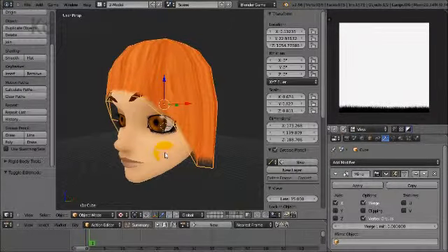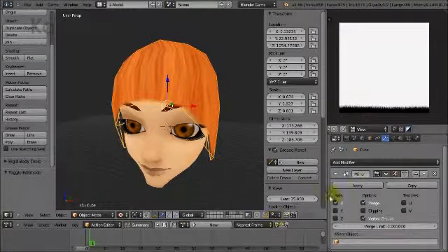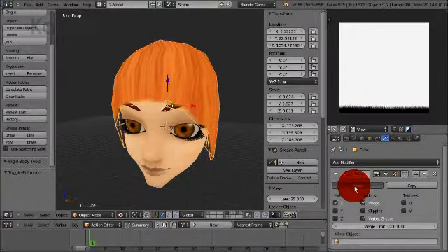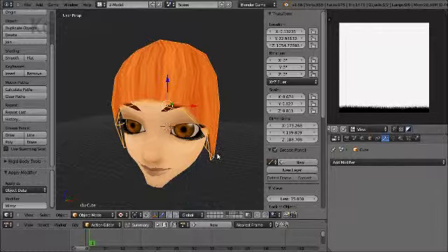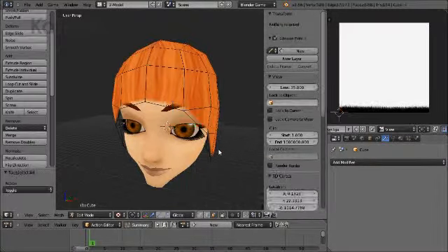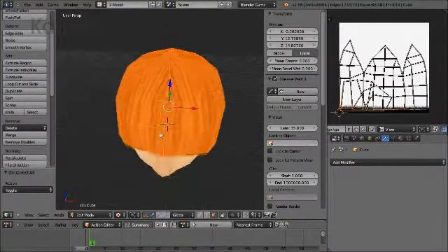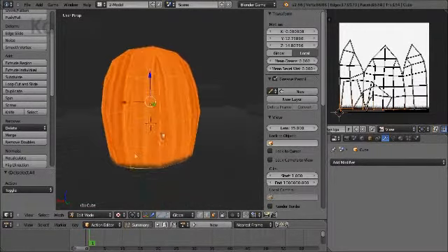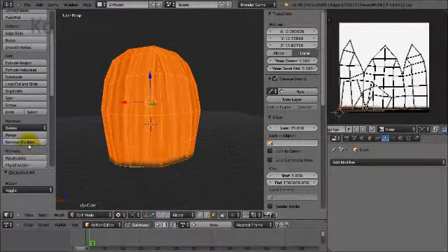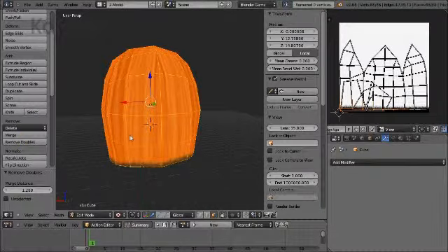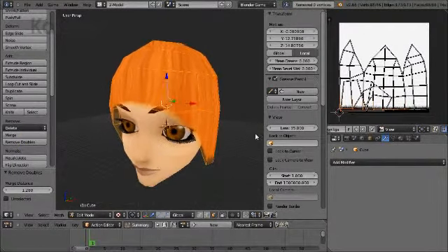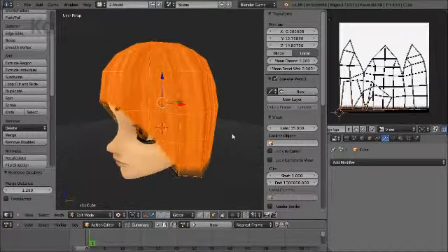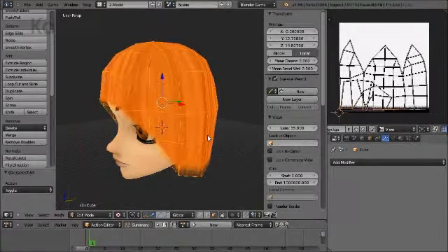Before doing that, we need to prep the mesh. So that means applying the mirror modifier, so this becomes one single solid mesh. Double check that the vertices along the center seam all closed and collapsed. Whilst in edit mode, make sure everything is selected.